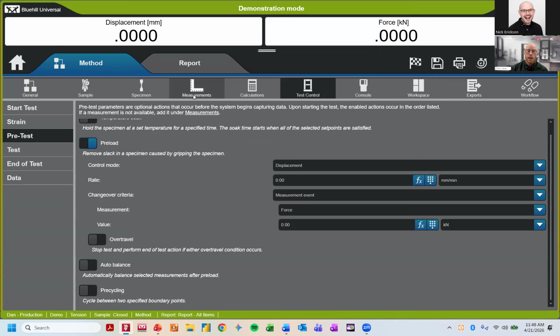So there's going to be mechanical limits on the guide columns of the system that you're going to unscrew, screw, to a point where if the crosshead comes down beneath that, it'll make contact, disable the frame, prevent any further movement. So you can do that on the low end, you can do that on the top end as a mechanical stop for the crosshead, which in essence is the grip's travel limits.